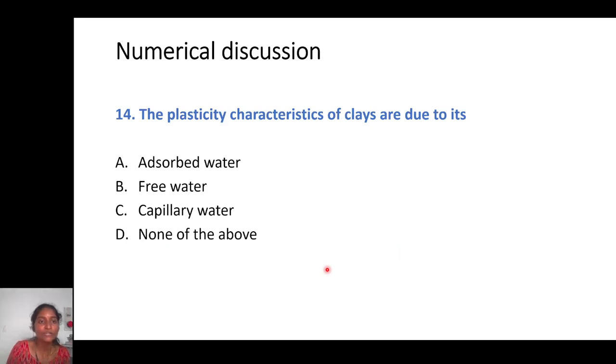Okay, in continuation to that, let us say if I have a soil and if it has a more diffused double layer. When I say more diffused double layer, is it a weak soil or not? It is obviously a weak soil, because more diffused double layer means more amount of expansion. So we wanted to avoid that.